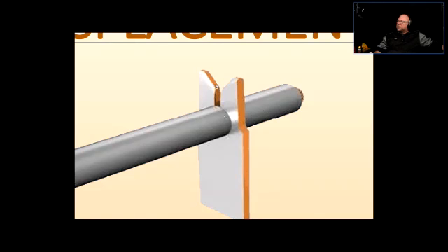So we are placing a conductor right on top of the connector, and you're using something to push it down, usually called a punch down tool, right? You're pushing the conductor in, the slot opens slightly and then it closes onto itself again, and the connector is biting through the insulation and making contact with the conductor that's inside. IDC, so insulation displacement connection, right?